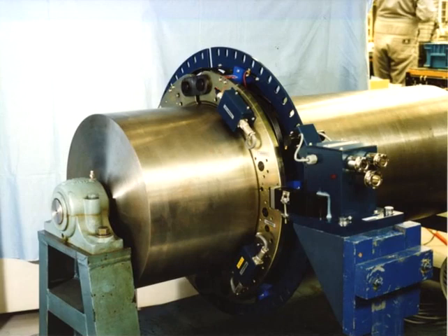This is a torque meter that employs a sensor containing a special alloy. When shaft distorting force is transmitted to the sensor, its length changes slightly. With this torque meter, it is possible to measure torque by detecting the slight change in the sensor's length.